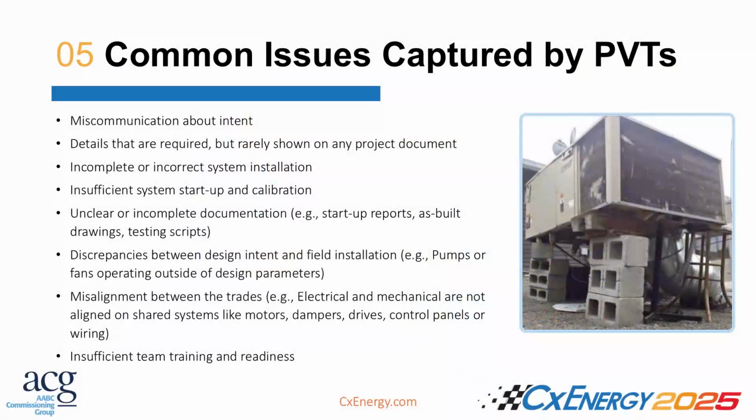It's just an opportunity for everybody to get their hands on it, like we've been stressing this whole time. It's a chance for that, and also to see where the system sits. If a pump or a fan runs and it doesn't create the static pressure or the differential it needs, it's going to signal that something else isn't right. Even though you went through the startup, it doesn't mean that the system works right away. The valve's open, balancing wasn't finished, they overrode all the valves, and nobody would know it. Things like that. So it's a chance for everybody to get in line and show everybody that they're competent and did the job that they were asked to do.